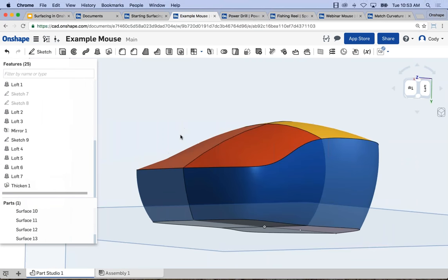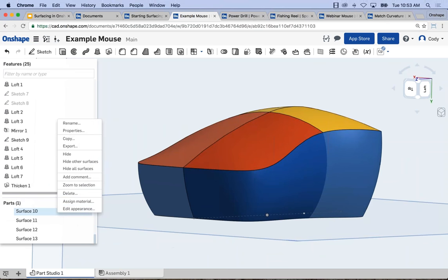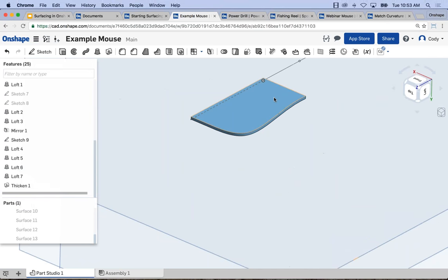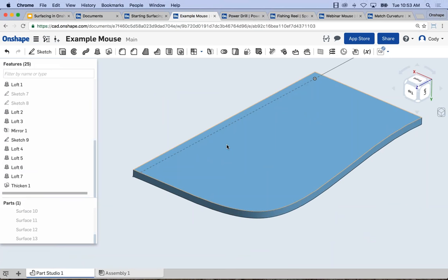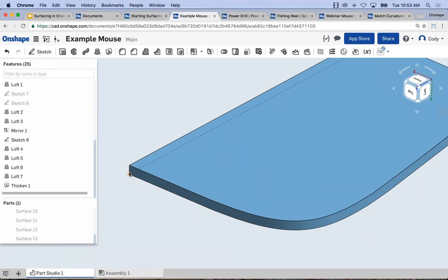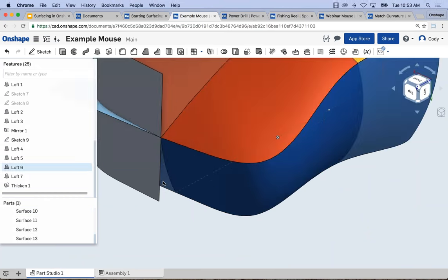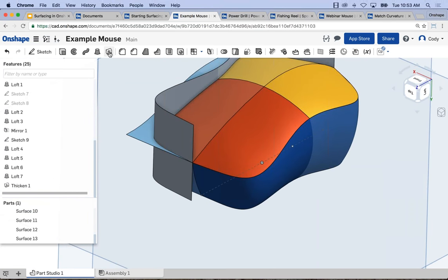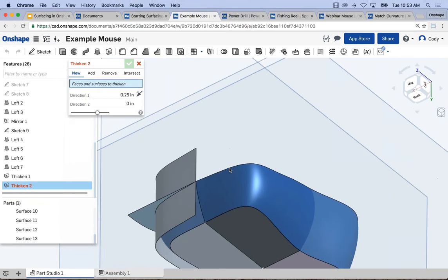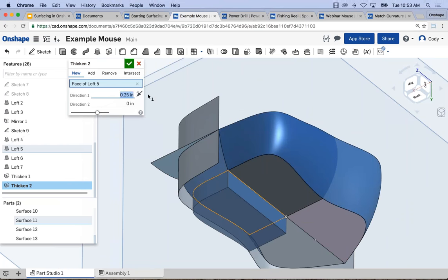Okay. Now, in this case, it's thickened it up, so let's hide all the surfaces. And there's our thickened surface. Now, it's only 30 thousandths thick, but maybe it's an injection molded part where it has that uniform thickness. So in this case, that's really all there is to it. You can grab the surfaces, convert them with thicken. All it is, is a matter of defining the amount of offset that you want.